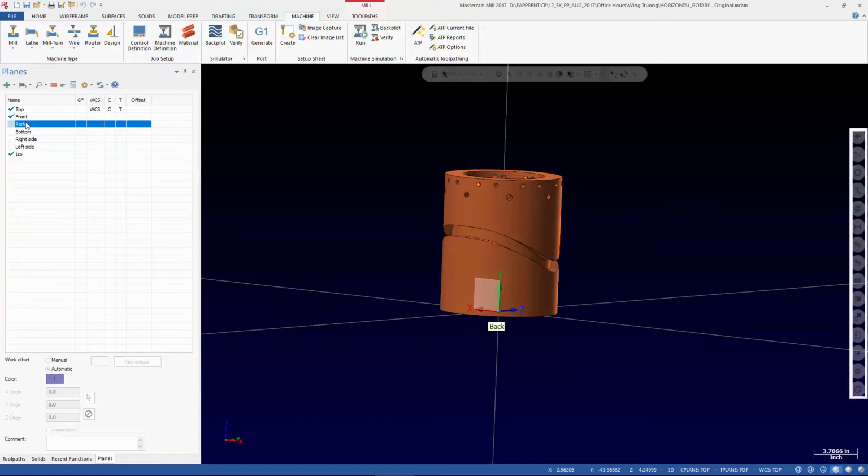What you have to have is a single vector that remains constant when you are programming for a 4-axis rotary. It doesn't matter if the 4-axis rotary is vertical, rotating on X, vertical, rotating on Y, or horizontal, rotating on Y. One of those axes has to remain pointed the same direction. And if you look at bottom, Z-axis is flipped, but so is Y.